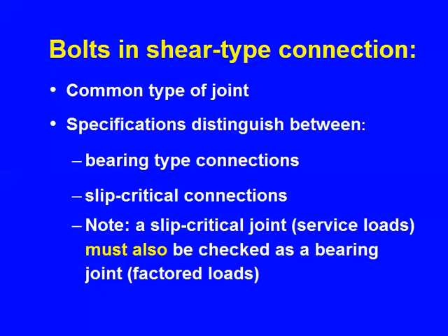In the bridge, slip could happen, but that's not the end of the structure. So that structure still has to be checked for, quote, shear and bearing, whether you're using LRFD or allowable stress design. We are in the slip critical category, that's the one I'm illustrating with. Yes, you have to check for slip, but after you've done that, you also have to check for shear and bearing at a different load level.